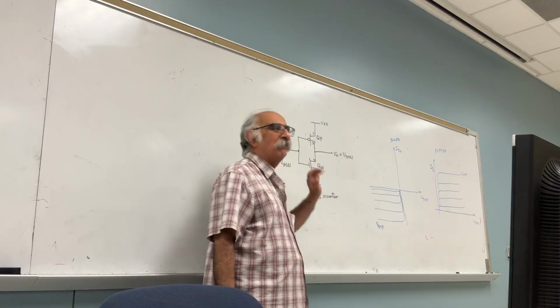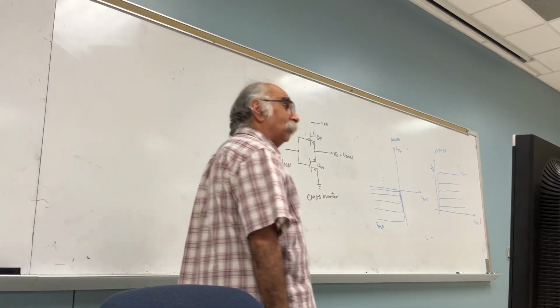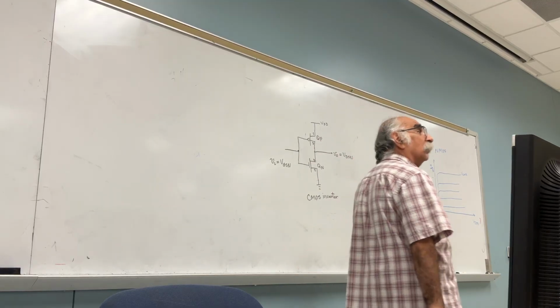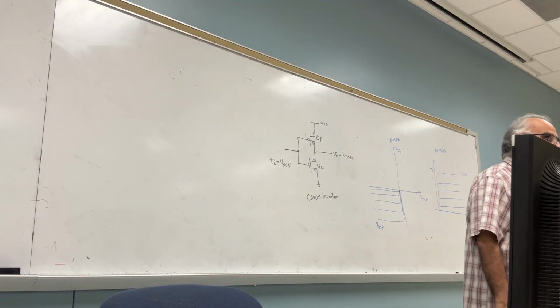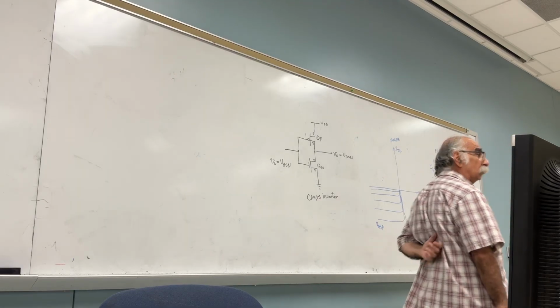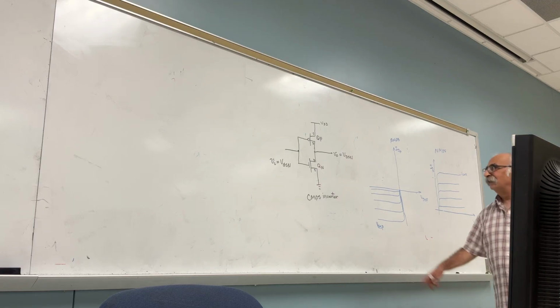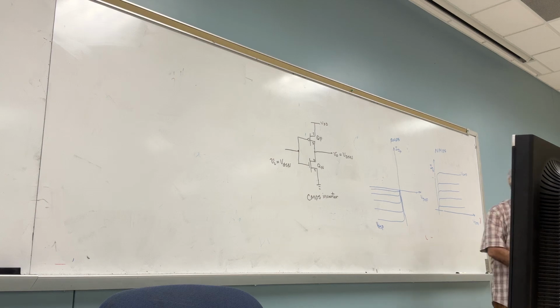We started talking about the CMOS inverter. Clear? We found out first of all that the resistively loaded inverter was not efficient because it results in power dissipation when the input is low. Did you follow me or not? It results in power dissipation. Let's see this one here and understand what we do.